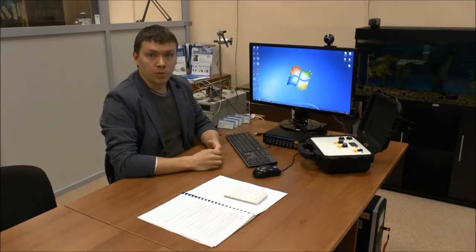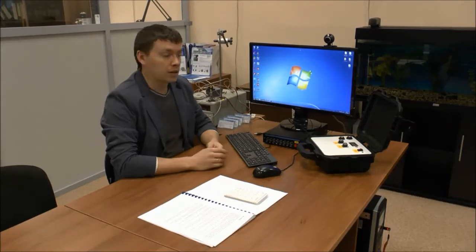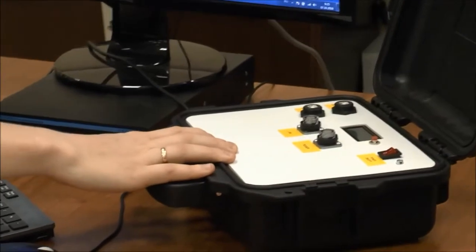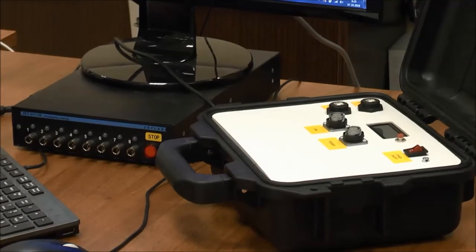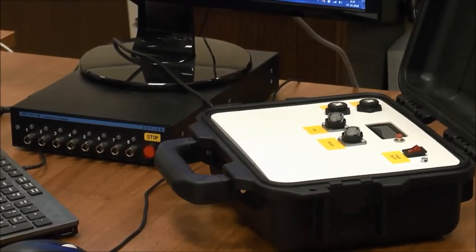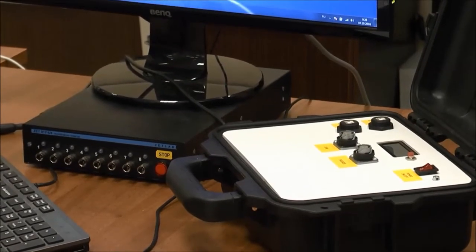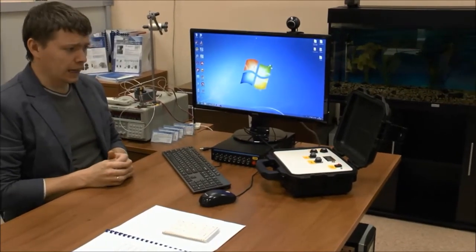ZET7155 digital geophones. The mobile system consists of offline recorder ZET7173 and additional seismic survey modules. The measurements were performed in 7 SPS. The distance between measuring modules was 15 meters. There were 8 sensors. And the seismic streamer was shifted at the distance of 15 meters.